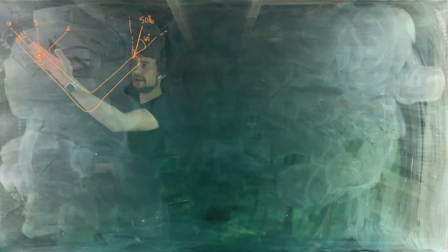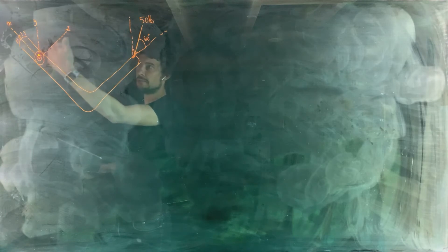Now I've put the label for point A on exactly where I want to put the axis here, which isn't great. So there's the other axis coming up with that line roughly parallel to that line, and then our other axis going back this way here. So the labeling on the drawing that I'm looking at is x-axis there, y-axis there, z-axis like that there. That makes sense according to the right-hand rule. Fingers in x, flip them up into y, thumb points towards z. Yep, checks out.